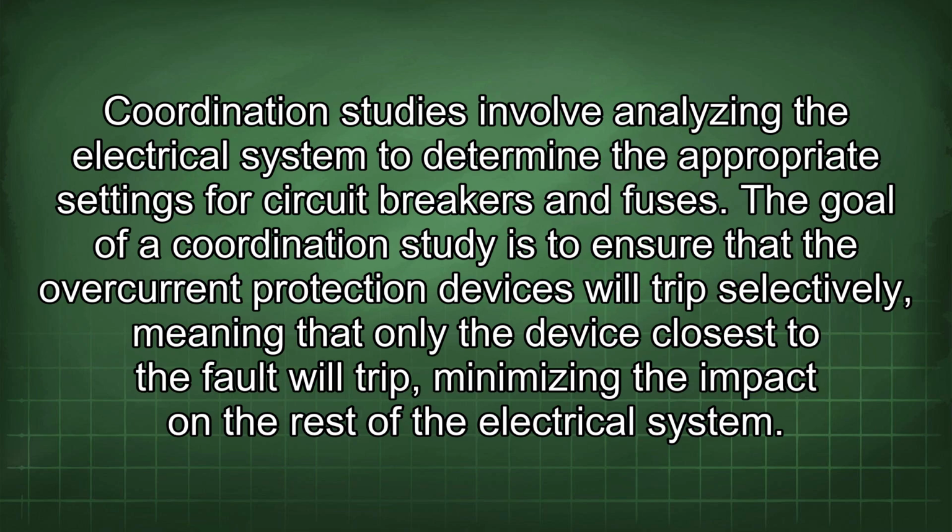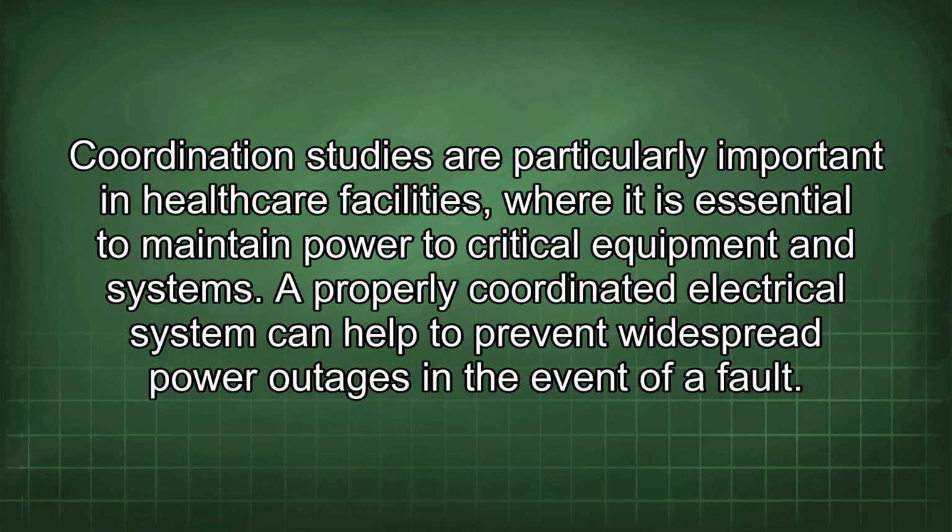The goal of a coordination study is to ensure that the overcurrent protection devices will trip selectively, meaning that only the device closest to the fault will trip, minimizing the impact on the rest of the electrical system. Coordination studies are particularly important in healthcare facilities where it is essential to maintain power to critical equipment and systems. A properly coordinated electrical system can help to prevent widespread power outages in the event of a fault.